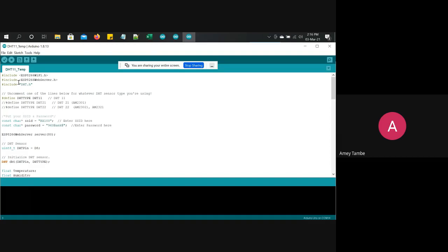So here you can see I've included two header files. One is Wi-Fi and another is the web server. Now, Wi-Fi is very important, as it can open up the ESP modules and start communicating. Another one is the web server header file, ESP8266 web server. So once we attach the web server header file, it works in both connections, the active and the passive. So yeah, I can make it connect to the existing access point.